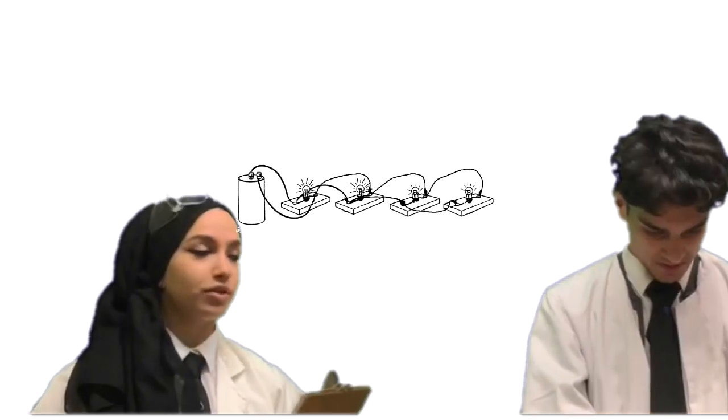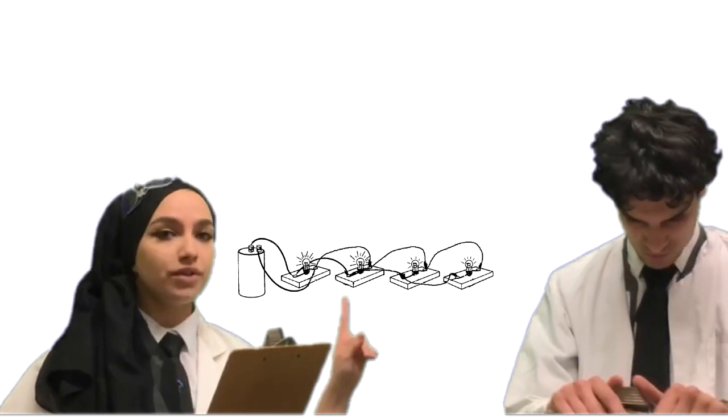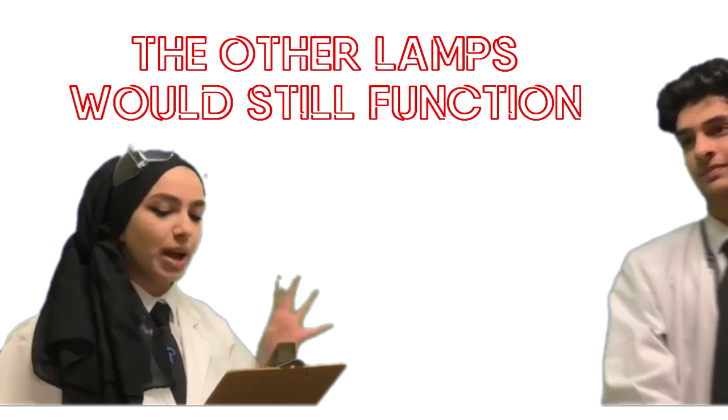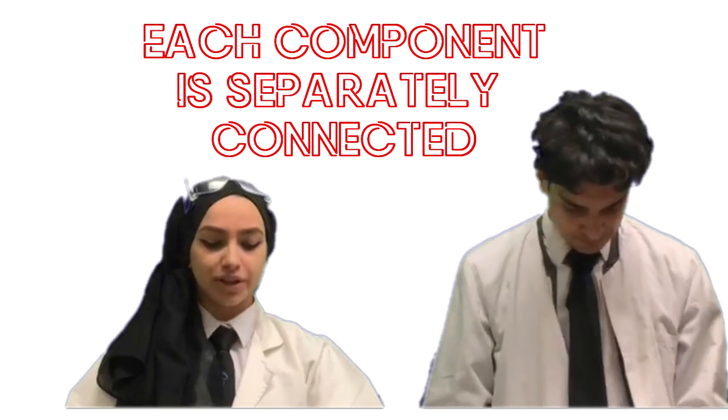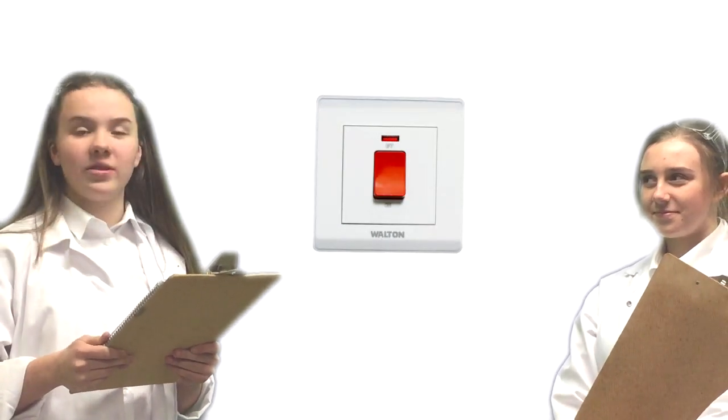Well, for example, if I had 4 lamps in a series circuit and one of them broke, all of them would stop working. On the other hand, in a parallel circuit, if one lamp stopped working, the others would still function perfectly fine. And also in parallel circuits, each component is separately connected. Most things are connected in parallel, for example, in household electrics and in cars. This is because you have to be able to switch everything on and off separately.